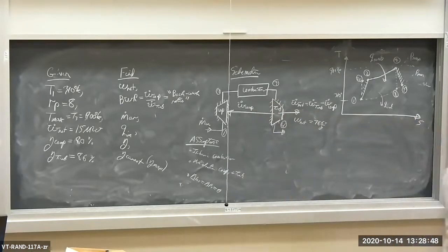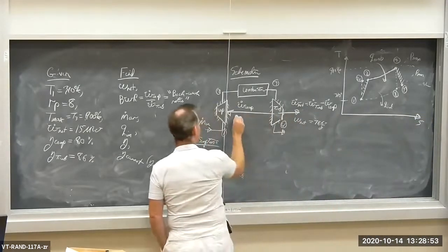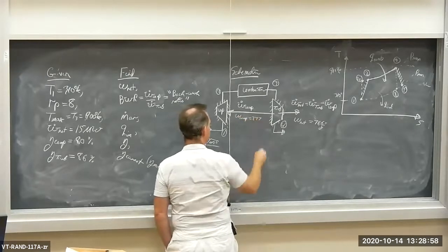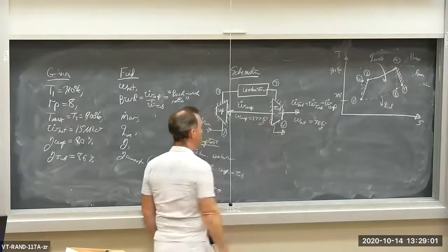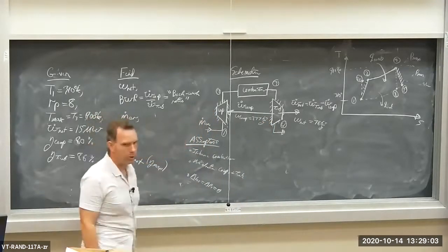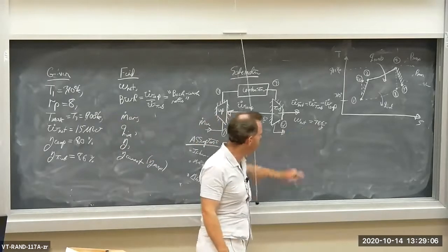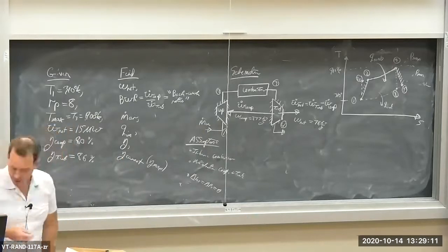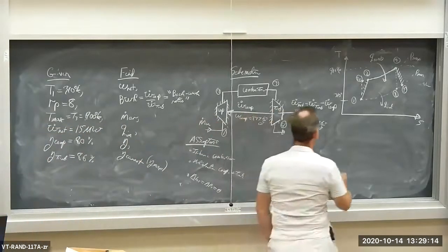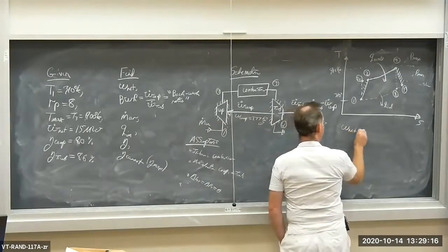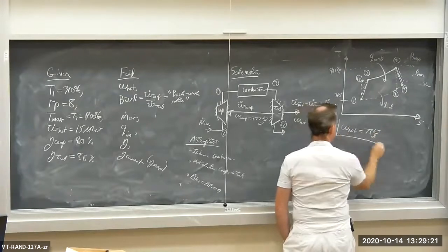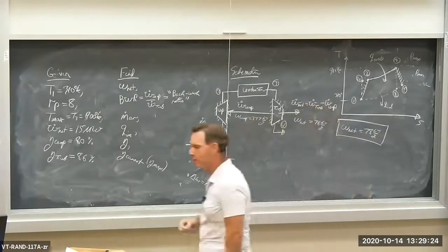The compressor work is 277 kilojoules per kilogram, and of course, the turbine work is 277 plus 78, which was 355. Okay, so let's box this up somewhere. So W net is 78 kilojoules per kilogram.